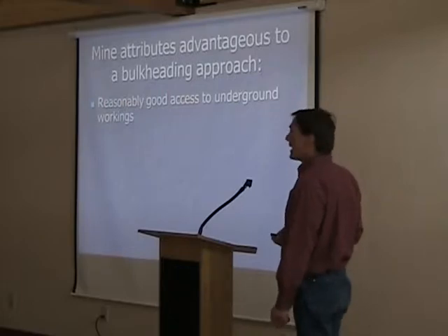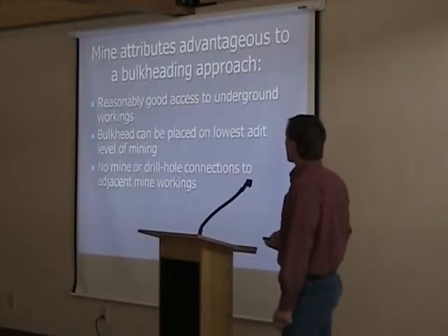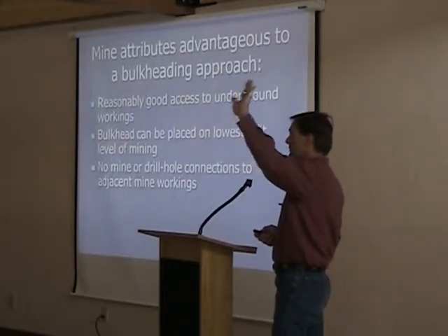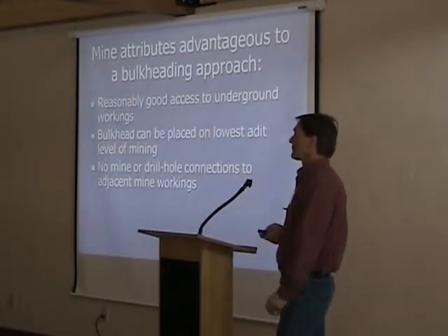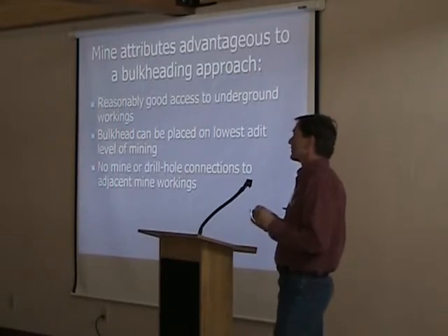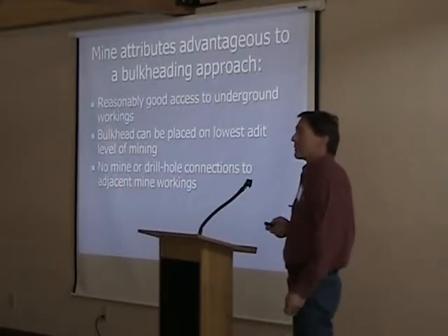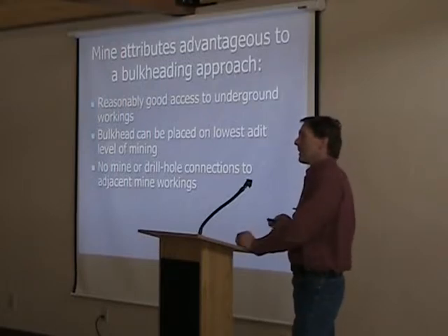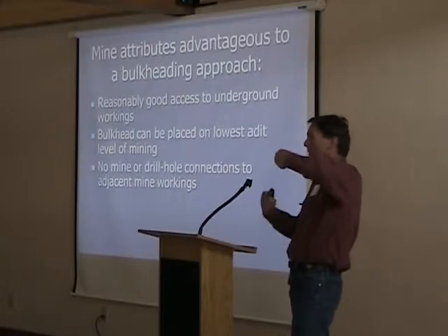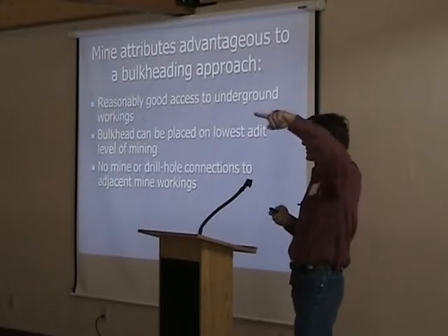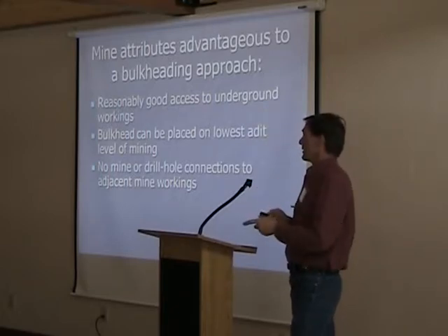So some of the main attributes that we want to have is reasonably good access to the underground workings. If you've got hundreds of feet of collapsed timbers and cave rock, that's something that's going to probably prohibit you, if that's the only way in underground, of knowing how we can evaluate the underground system. The other thing that we're finding, and is pretty true, is that bulkheads really only work when you put them in the lowest hole in the barrel, the lowest spot on the mountain. If you put it up higher and there are other holes that are connected, obviously that's not going to work because the water's just going to flow downhill and come out in another area.